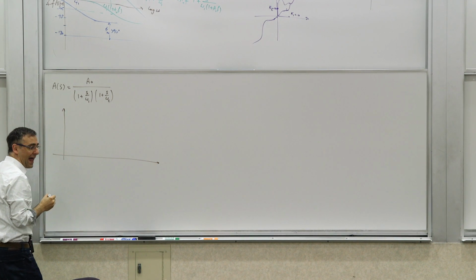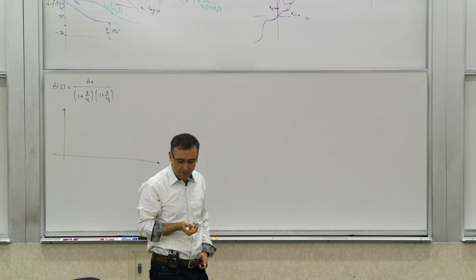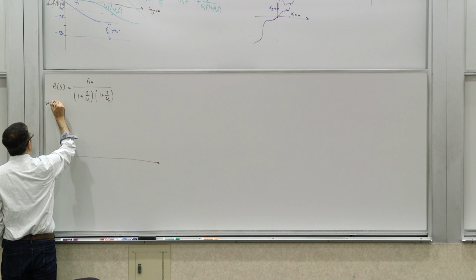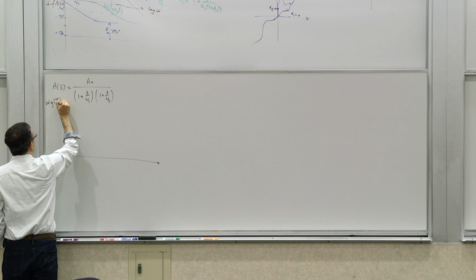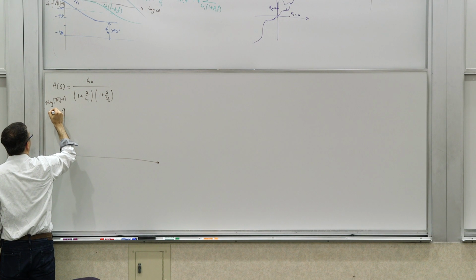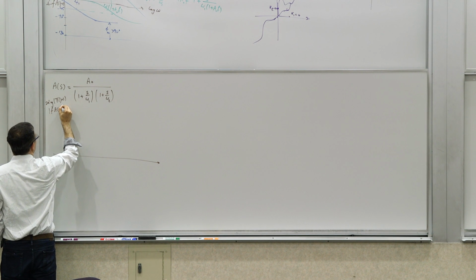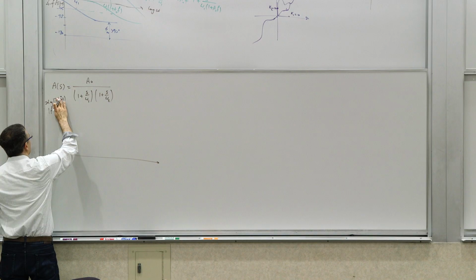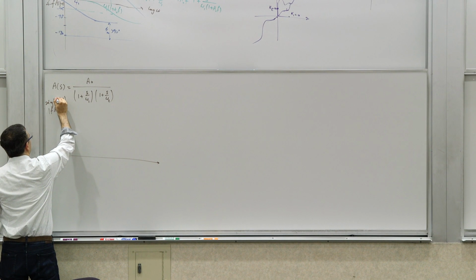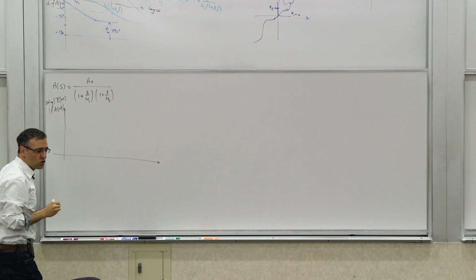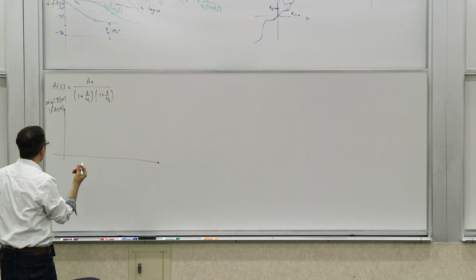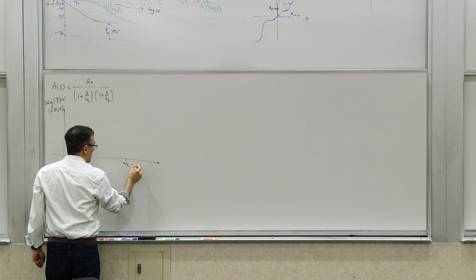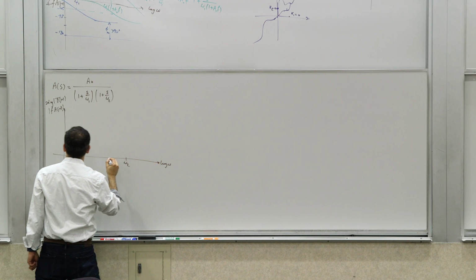So essentially we are looking at the magnitude and phase of the loop gain. So magnitude is 20 log base 10 of the loop gain of j omega, which you can actually write as f times A of j omega if f is constant, not a function of frequency, but in general it could be, so you can write it generally as a loop gain with this capital T defined here. So you have two poles, right? Let's say at omega 1 and omega 2. And this is log of omega. So what do you get?